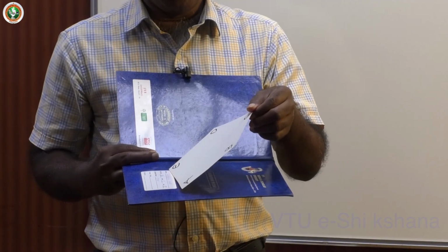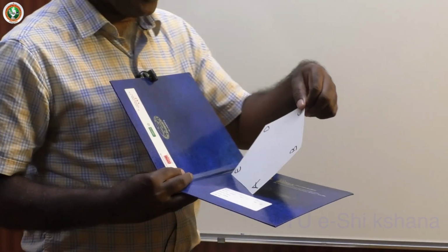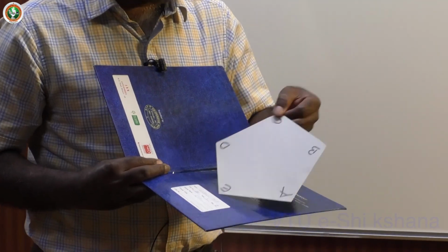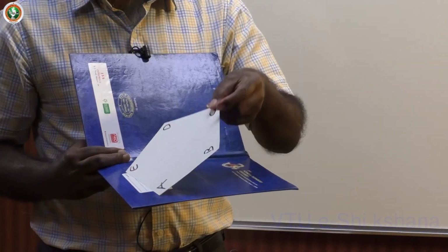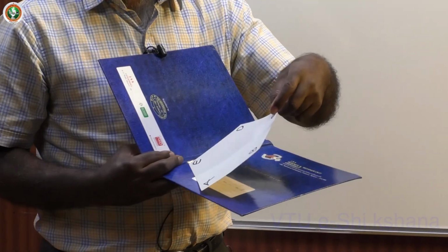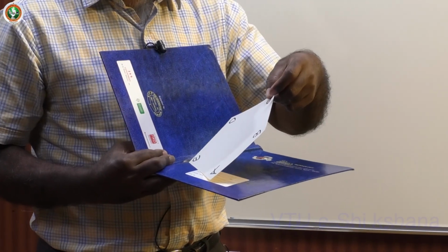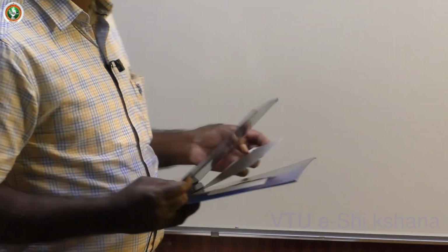Okay, and the edge on HP is inclined at some degree to VP towards the XY line or away from the XY line. If the situation demands, then only you do this. Otherwise, you always better take this. So first position, second position, third position. So this is how you get the problem solved. This is the change of position method as usual. Now I have a problem.